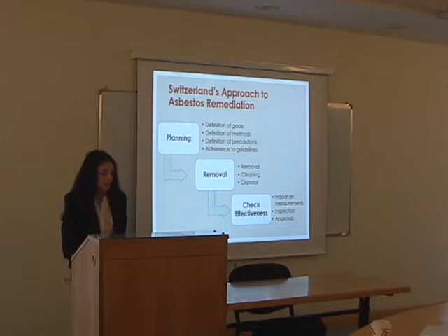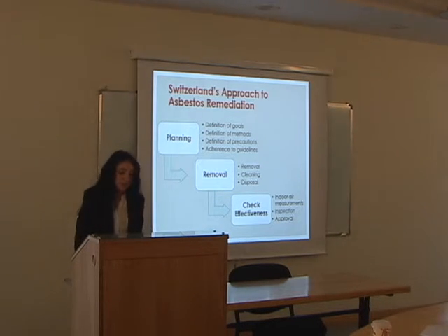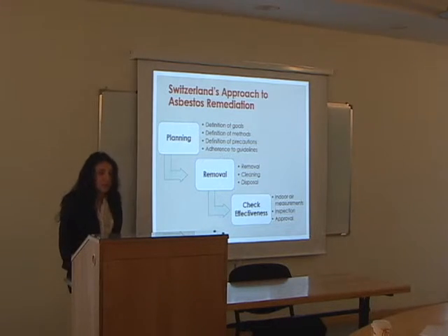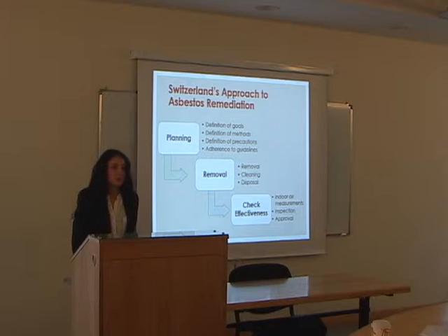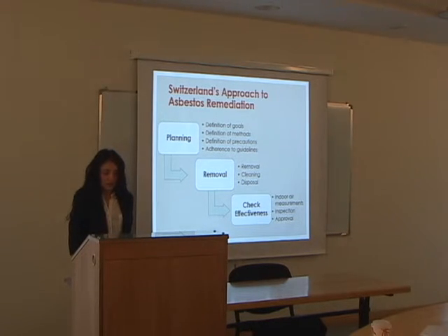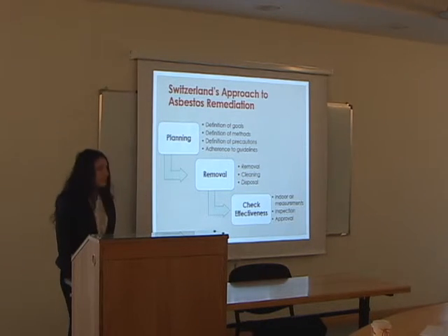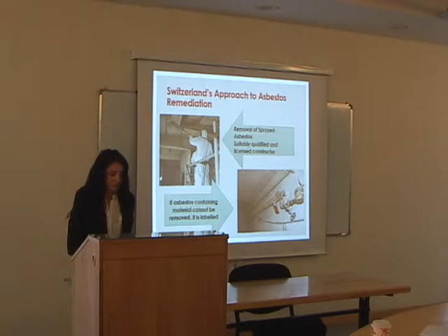Then the removal activities are done: removal, cleaning, disposal, and, which is very important for them, checking the effectiveness of their work. And they routinely do indoor air measurements, take samples, do inspections, and approve their work.